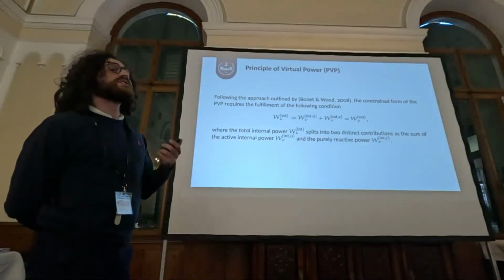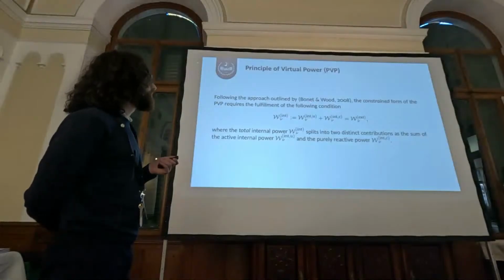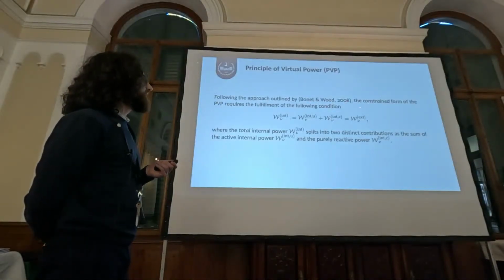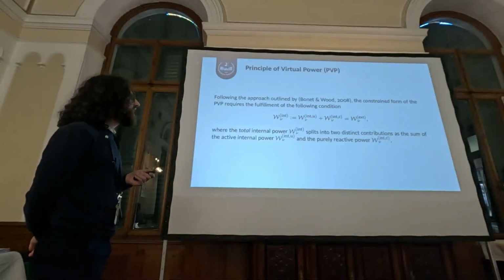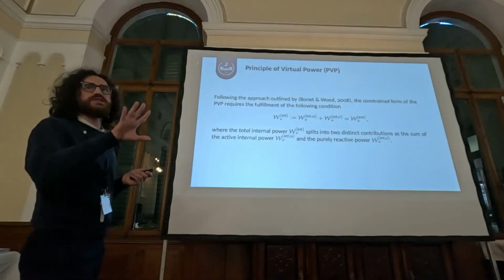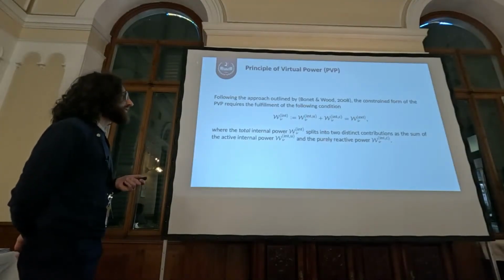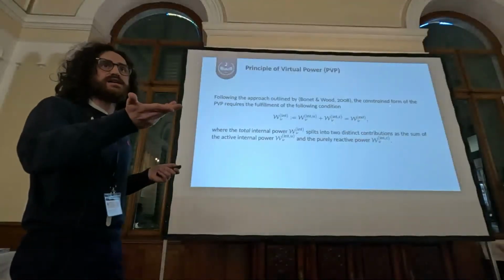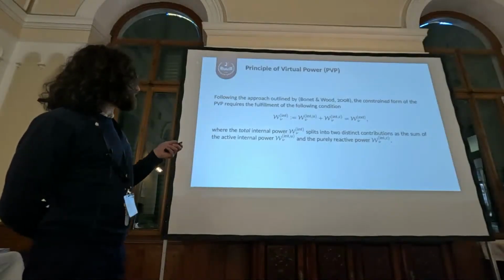At this point, we have all the ingredients to follow the approach outlined by Bonet and Wood, who express the constrained form of the principle of virtual power, in which the contribution of the internal power is split into two different contributions. The first one is related to the active internal power, and the second one is related to the purely reactive power, which is also null for the hypothesis that we introduced before.